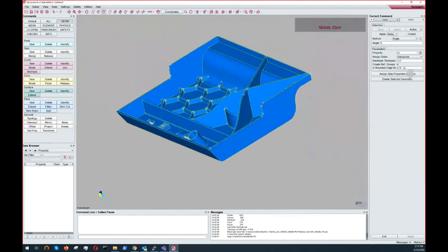Then there's another option here that creates reference groups. This is not so important for the command itself, but it's really, really useful for working afterwards and for checking the results. What it does is it creates a group of geometry for the volume selected and a group of geometry for the created faces, so the middle ply. And it makes it really comfortable to use afterwards, because you can change the styles and so in a faster way and check the model really easily.